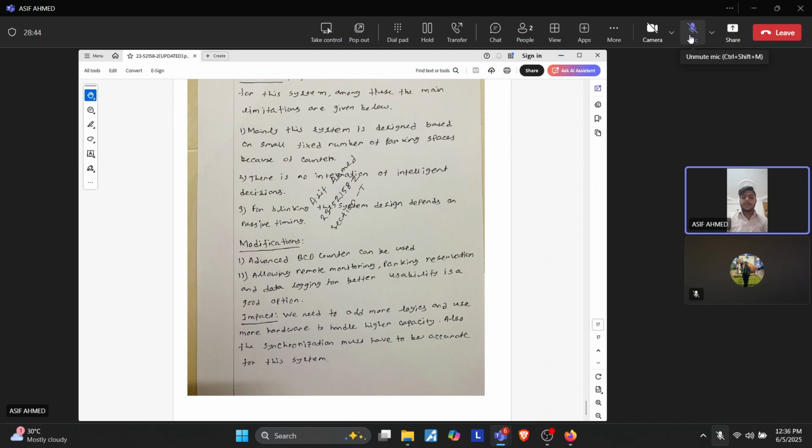First, the 4-bit counter restricts us to a maximum of 15 cars, which is not enough for larger parking areas. Secondly, the 555 timer has no enable pin, so we cannot pause or restart its output directly through logic control. Thirdly, the display is limited to basic messages on 7-segment displays.